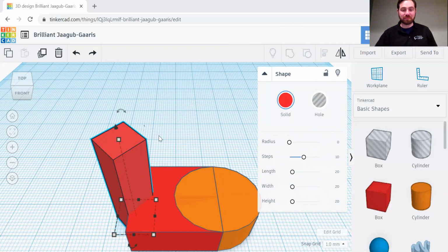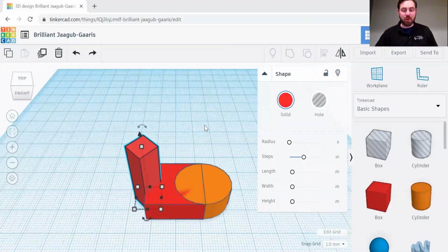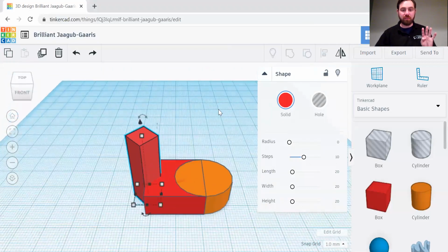So we've got our one tower. We're going to create 4 more towers to give us a total of 5. There's a couple ways you can do this. One way, make sure the tower that you want to duplicate is highlighted, and you can just click on it to make sure. You want to make sure nothing else is highlighted, nothing else has a light blue hue around it, just your tower.